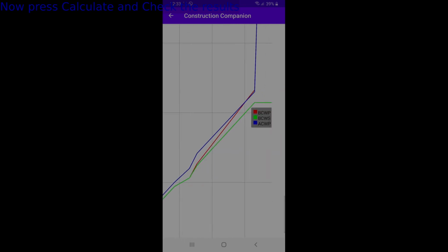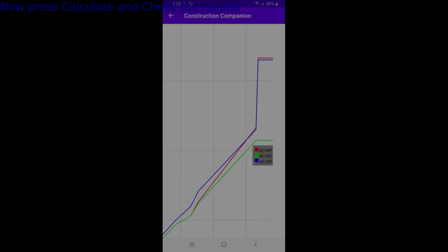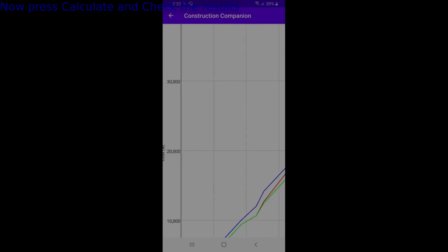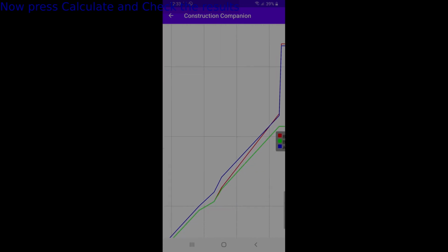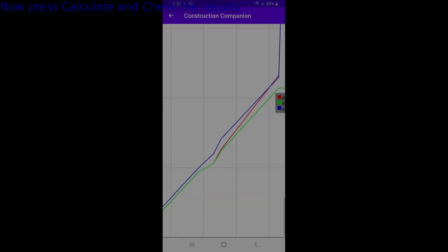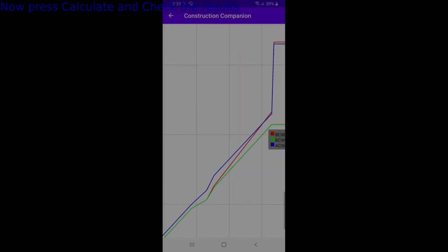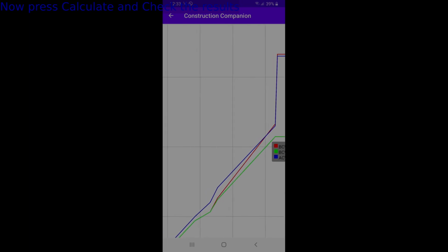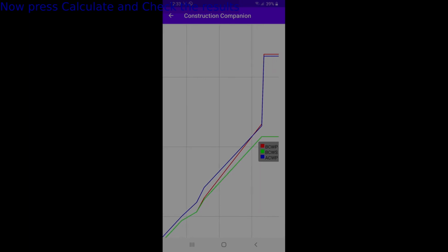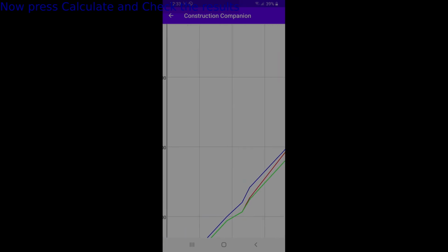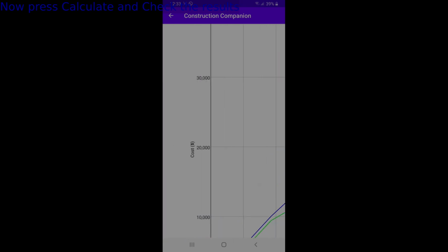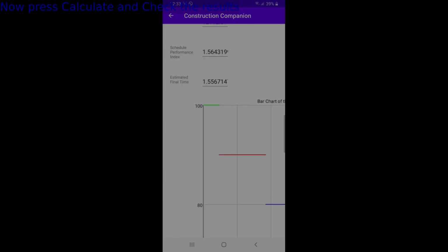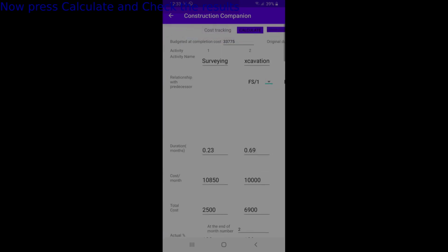Because a lot of stuff can go wrong in a construction project, it can be hard for the project manager to know how he or she could do better for future projects or even to troubleshoot problems in a current project. The S-curve brings you most of what you need in control versus time, so you can troubleshoot easily and precisely which activity has caused this, what the issue is, how it could be solved for this project, and how it could be prevented for future projects, along with many other benefits of the cumulative cost curve.